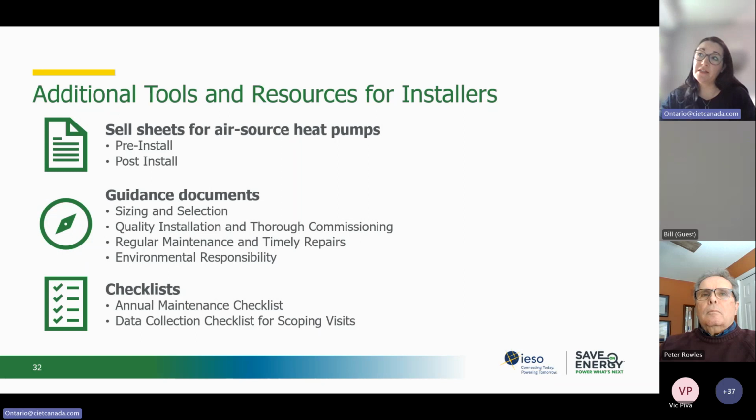Someone asked, is there a difference between a cold climate heat pump versus an air source heat pump? And that's just it. It's how cold can it be and have that heat pump keep up with the loads. So Peter was describing earlier, both the coefficient of performance and the capacity of the units degrade as it gets colder outside.